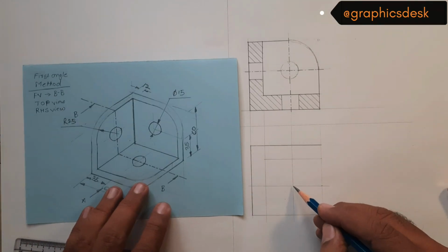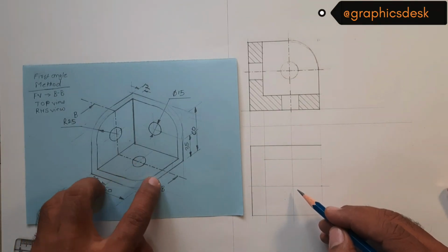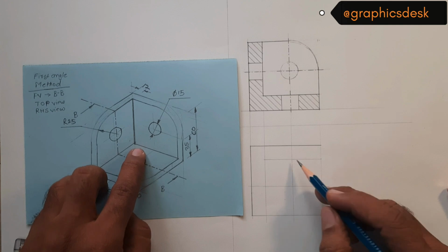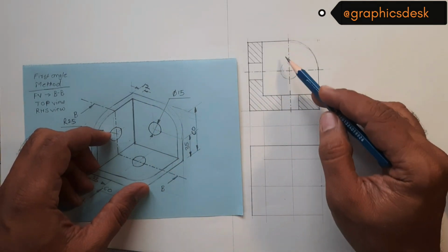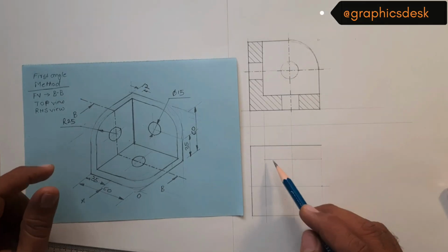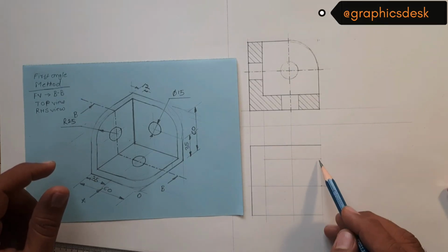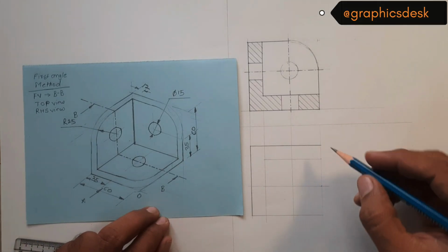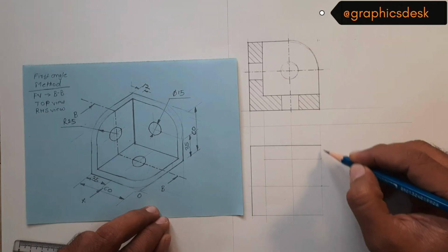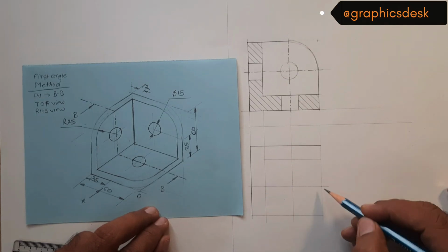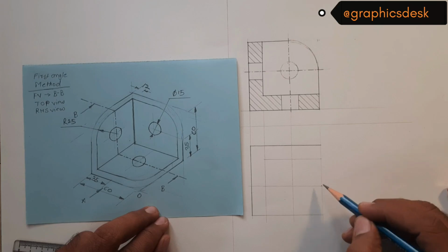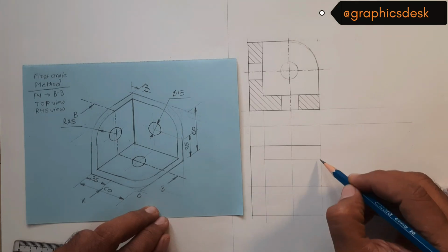So this one is now the center for this particular arc and this particular hole, whereas this line is representing this entire face, which I've already drawn in the front view. But here in the top view, it will be represented as a line. So what part of it would be solid is this particular line until this point, this particular line until this point, and there will be an arc of 25 mm here. This will be solid and this will be solid.